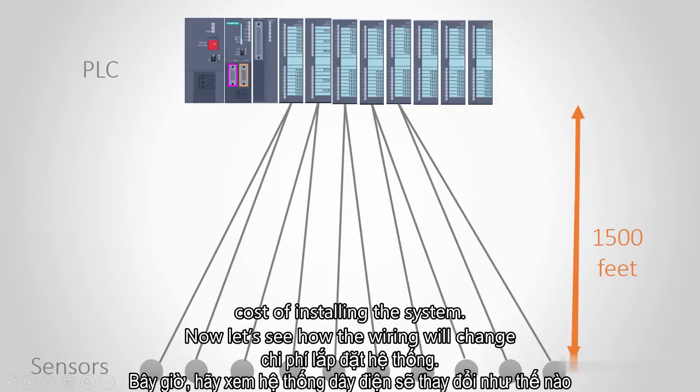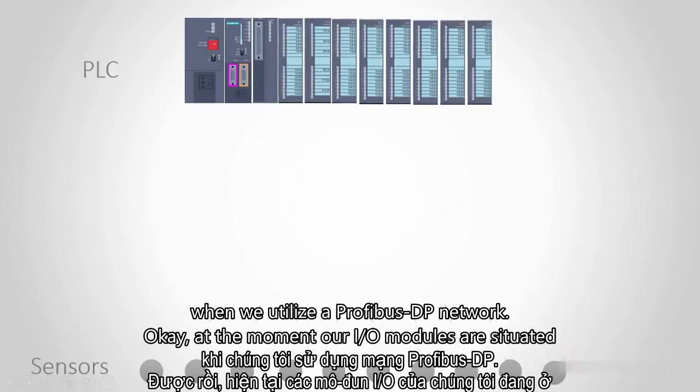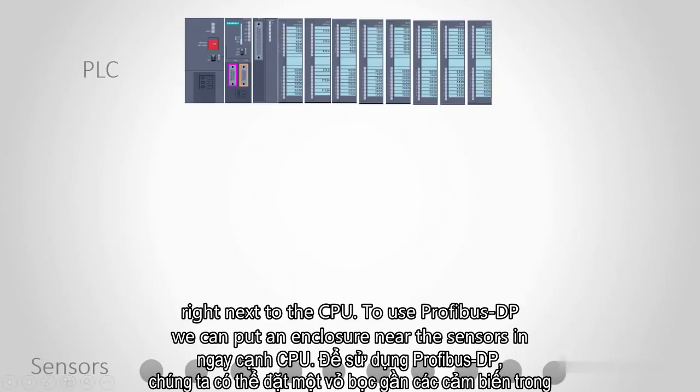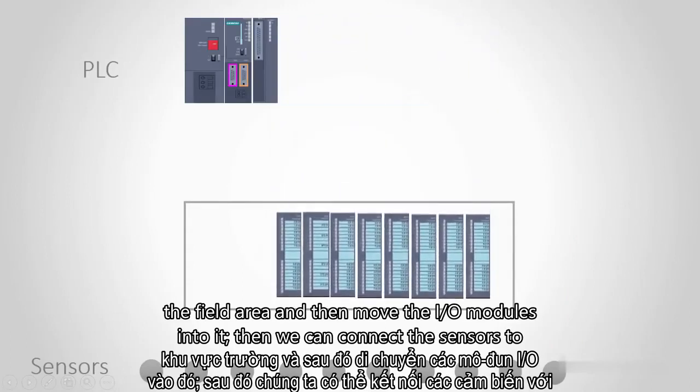Now, let's see how the wiring will change when we utilize a Profibus DP network. Okay, at the moment, our I/O modules are situated right next to the CPU. To use Profibus DP, we can put an enclosure near the sensors in the field area and then move the I/O modules into it.